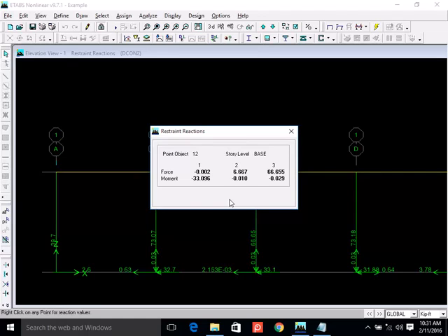What about the third axis, which is vertical, passing through the centroid? Movement about that axis, if any movement exists, is twisting movement. But because we don't have any lateral load or any point movement, we don't have twisting movement. Which axis is up? Three. What is the movement about 3? 0.029. That is actually torsion. So we are quite sure that torsion would be absent, if I am not wrong in terms of axis.